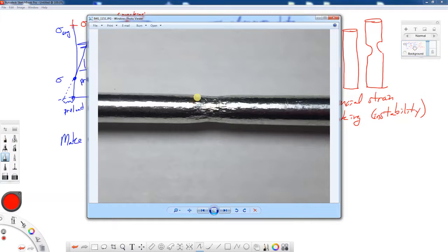In fact, we no longer have a uniform strain distribution along the axis of the bar. We no longer have a uniform stress distribution either. Because of this indentation, we start to get a more multi-axial stress state. It's very much like a notch in a bar. And you can do different types of corrections, like a Bridgman correction and different things that you might do.